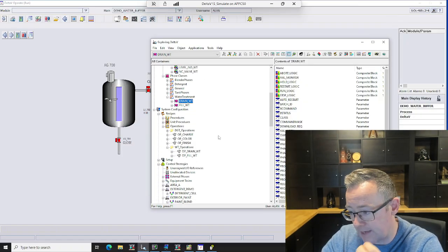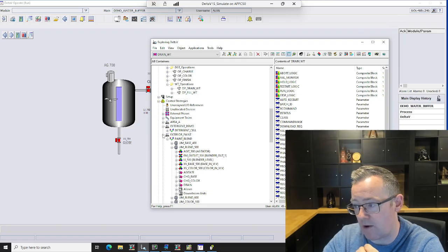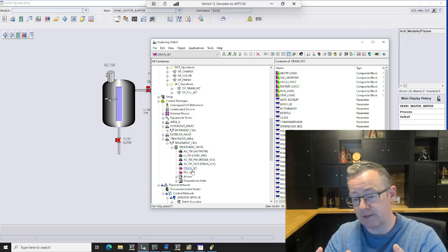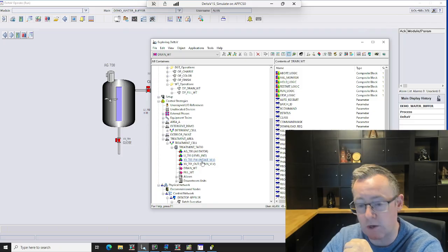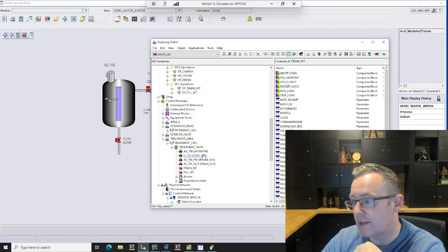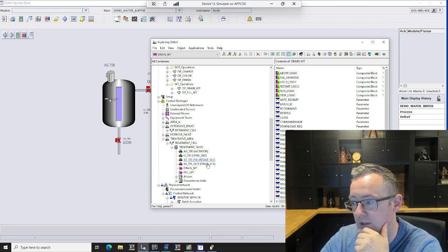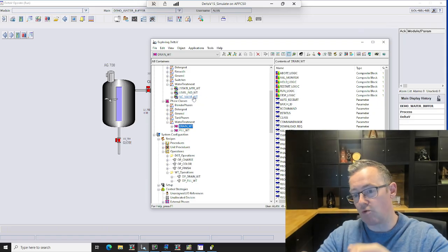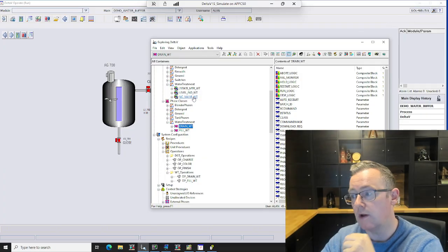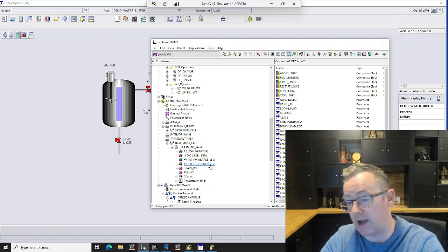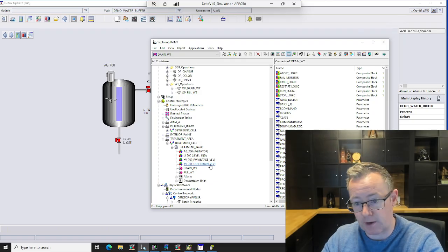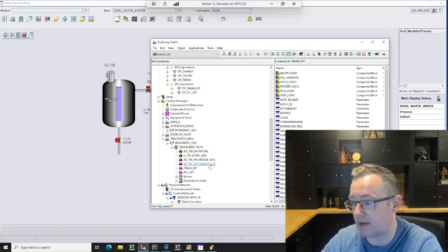Now we have areas which are created where we can combine our phases, and then combine our modules. That means we have a type of valve. These guys here, where we see both of these XV valves, are copies of this valve here, for example, and the rules apply to these instances down here as they're defined. So all of the rules and all of the settings in the background apply to these particular valves, and that's essentially it.